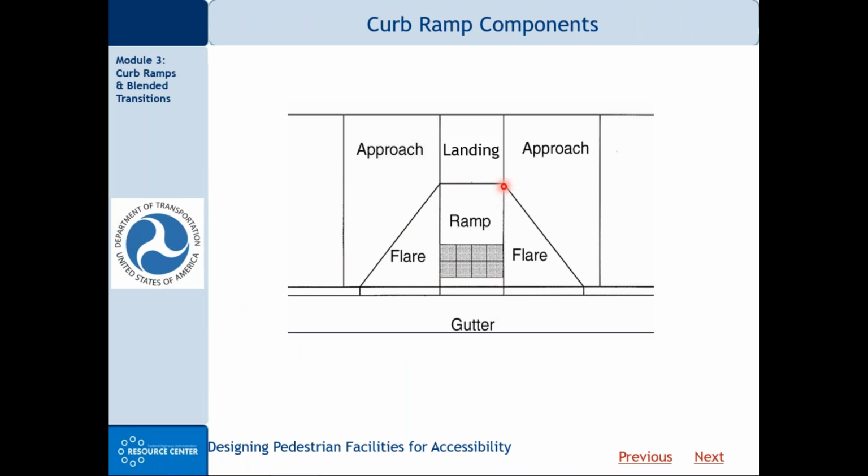This is the curb ramp. The grayish area here, these are the detectable warning surfaces at the base of the ramp. As we've talked about, there should be a level landing at the top of the ramp for turning onto and off of the ramp. And so it looks like this would be level, of course.